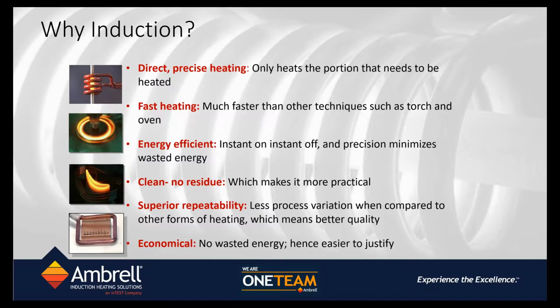So the energy efficiency of induction is a lot superior. Just imagine parts being heated with a torch. How much of the heat that is emanating from the torch do you really think gets into the part that you're trying to heat? Or in an oven, if you're putting the entire part in, and let's say you're in a brazing or a joining type process, not only is the part going to heat up in its entirety, any holding fixture or device that is holding the part that gets put in the oven is also going to heat up.